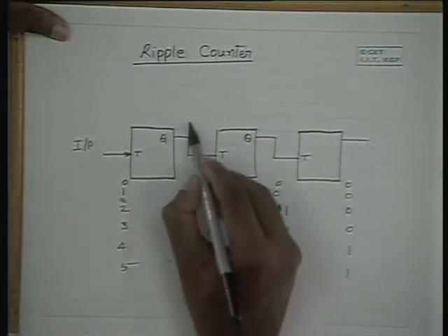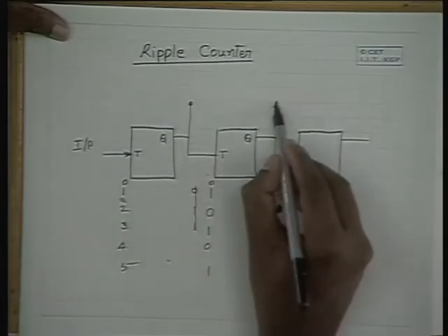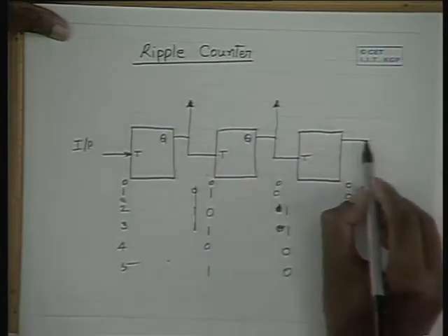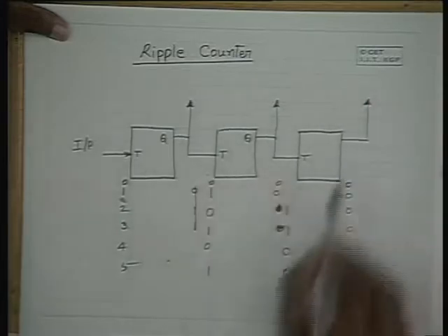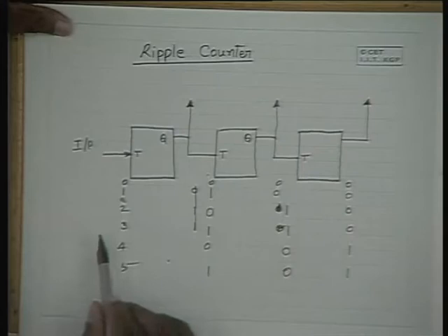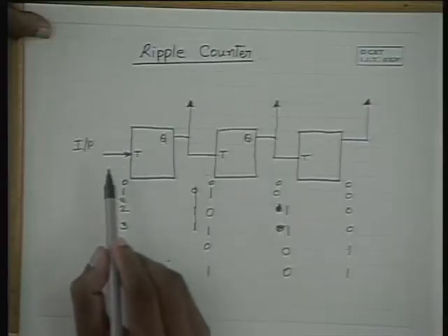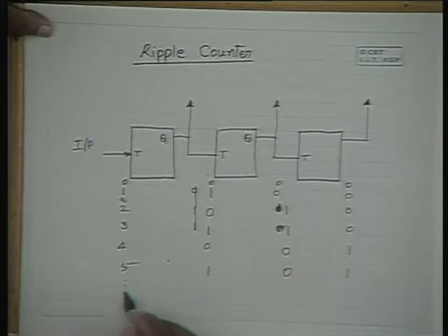Therefore, when you sample the binary counter outputs, these outputs give you the count of the pulses. Hence, it acts like a counter. It can count the input cycles. On the other hand, it works like a frequency divider also. So this is known as a counter. It can count up to 8 pulses, and for 8 again, all of them will become 0, 0, 0.